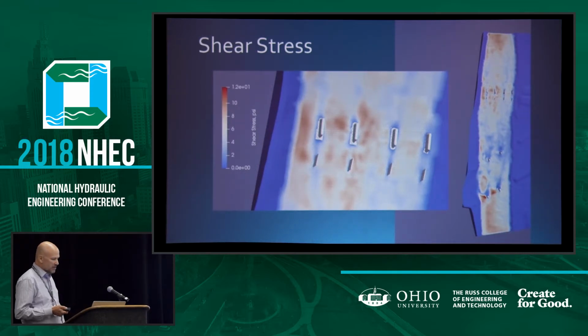This was our shear stress distribution. Again, looks like maybe there was some protection from this upstream pier because the blue is less shear stress. Of course, there's a little blue around each of these because there are some limitations on, again, these bluff bodies and how well the shear stress is predicted right there. It didn't really answer my question. Ultimately, the environmentalist said you can't put rock, so it didn't really matter.